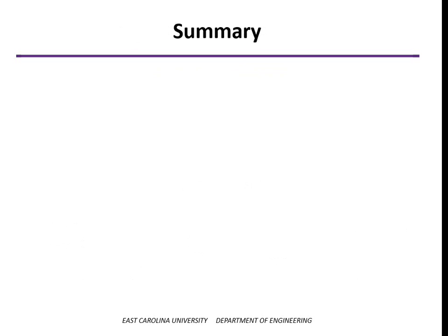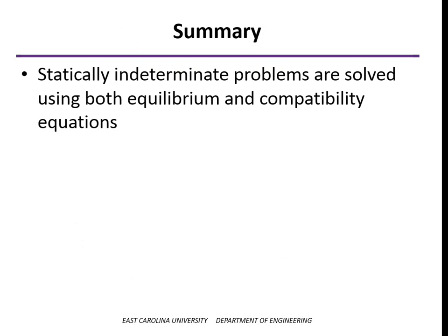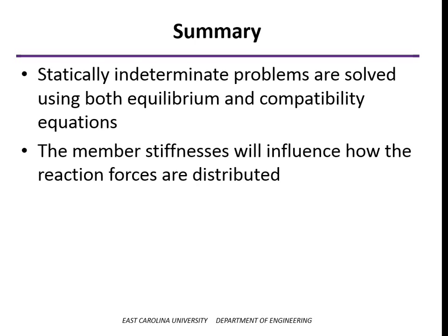So what we learned from that was that we needed to use both equilibrium and compatibility equations to solve for a statically indeterminate problem. And in the second part of that, what we saw was that when we change the member stiffnesses in a statically indeterminate problem, that will change how the reaction forces are distributed. So that wasn't the case in a statically determinate problem. It really doesn't matter what the stiffnesses were, but anytime it's a statically indeterminate problem, because you're involving displacements as well, then changing the stiffness of the members will change the reaction forces.